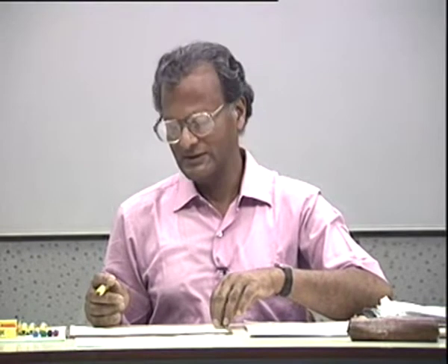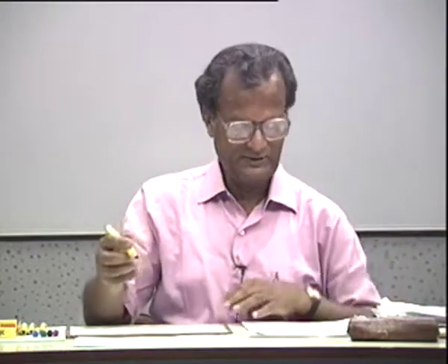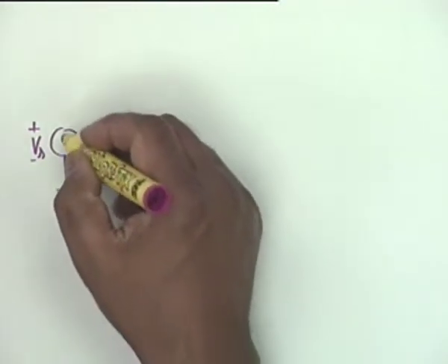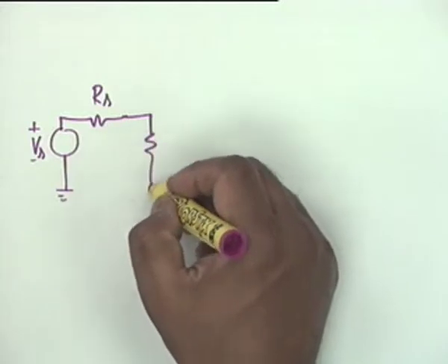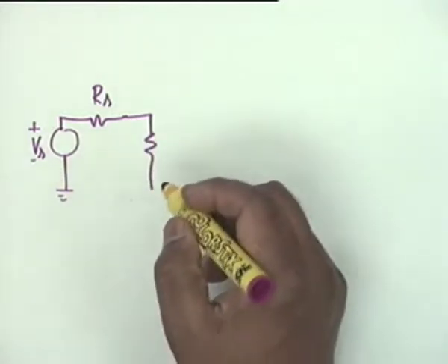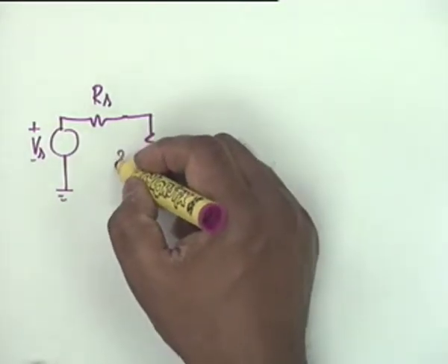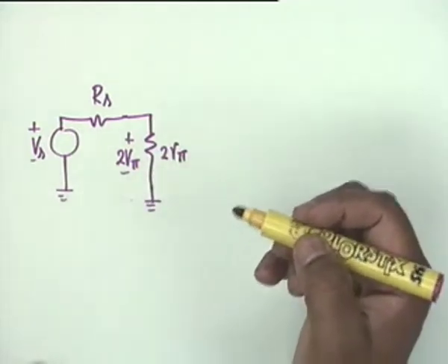We drew the equivalent circuit, and there was a very elegant result, namely that V pi 1 was equal to minus V pi 2, which made the equivalent circuit look like this. We had gone through this analysis, so I shall not repeat it. VS, RS, and then instead of an R pi, there is 2 R pi. The voltage across this is twice V pi, because one V pi is opposite of the other.